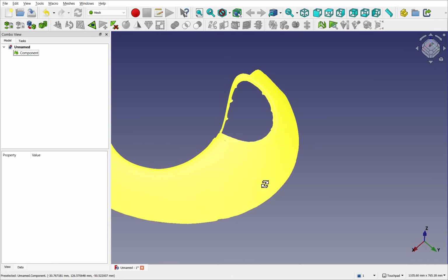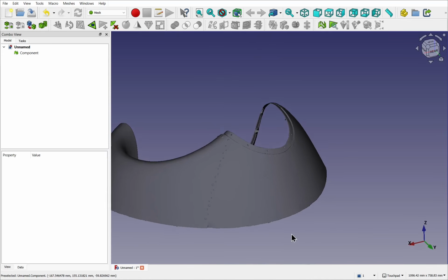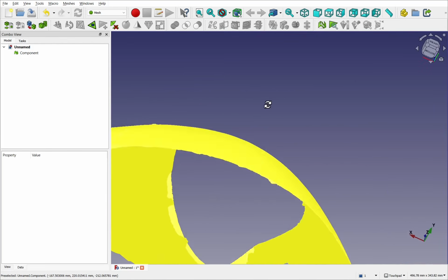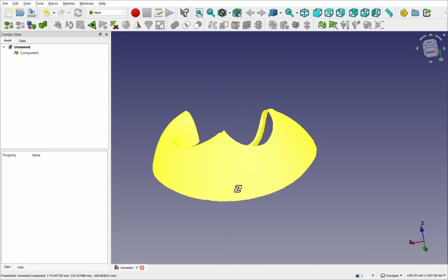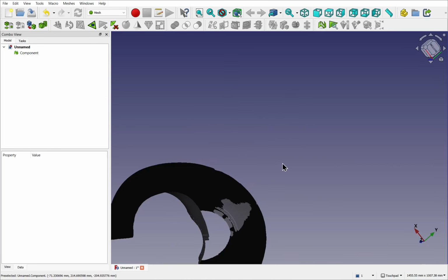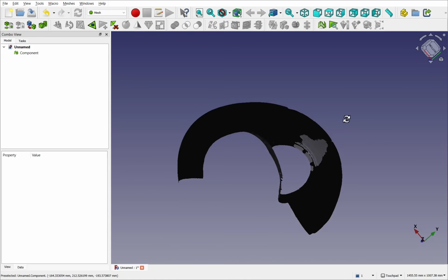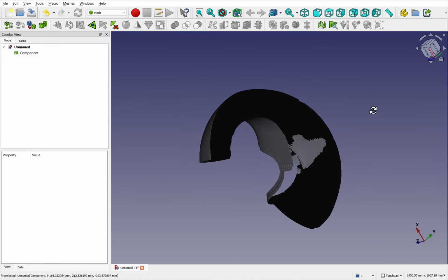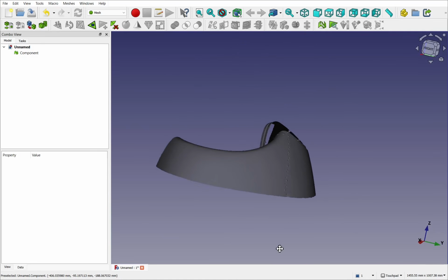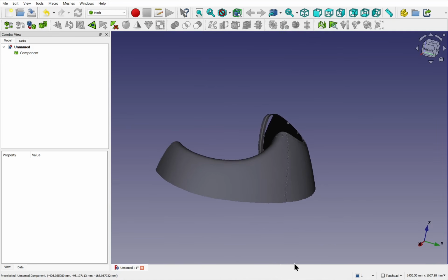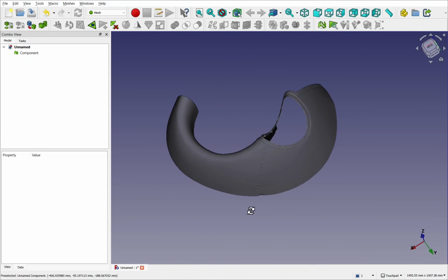With 3D scans, you'll find that you can go quite high on this, and straight away you can see that we haven't really lost any quality in here. Let's look inside and see what we've got. You can see we've got this patch here, which is a bit of an anomaly inside, which may fit our cross-section in. I'm just going to test the cross-section across that part there.